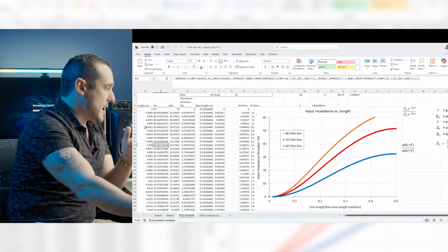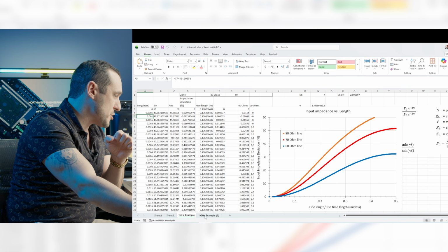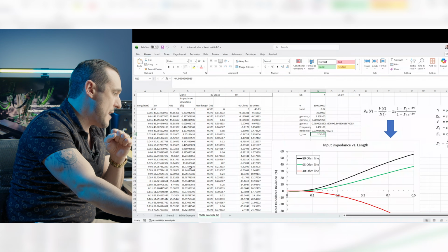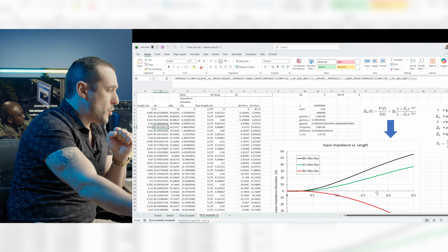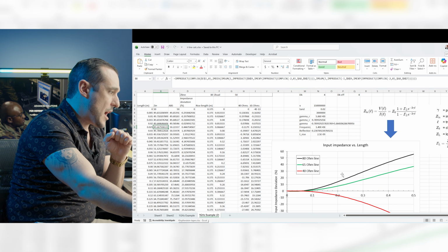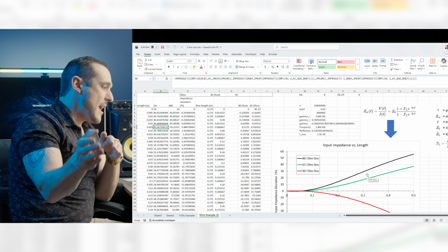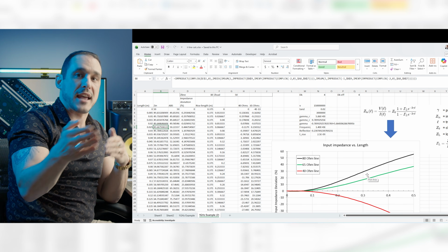So here's the calculator that actually gives you this result. You can see here that I have both of these examples programmed into this calculator. Here we have the 1 gigahertz example and then our second 1 gigahertz example shown down here. And what you can do is put in different values for transmission lines and a target impedance, and it will calculate the input impedance, and it will give you a percentage deviation from your target impedance for that input impedance.